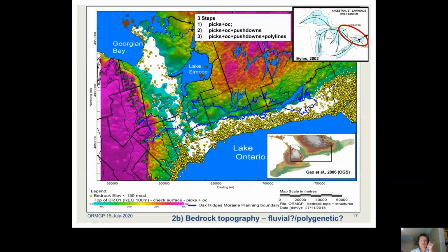Another thing that we do, and I mentioned, well, I didn't mention it, but I should have, is that when we correct surfaces for crossovers, etc., we have to set up a hierarchy of what's the most important. So, for instance, the DEM, we know that because you can see it, it's measurable. Our next important surface is the Bedrock Valley or the Bedrock Topography, because we're, like I said before, constraining our lower sediments within a bedrock valley.